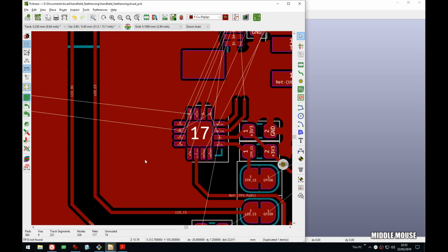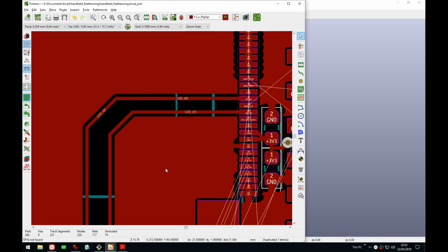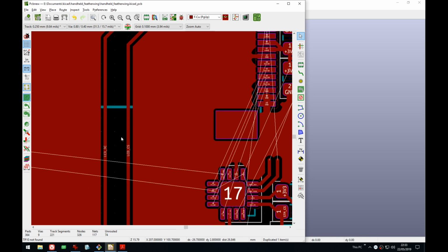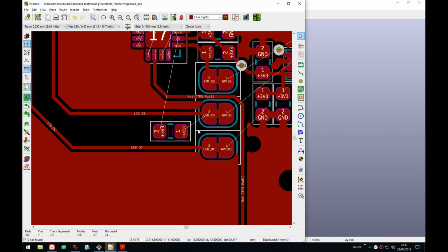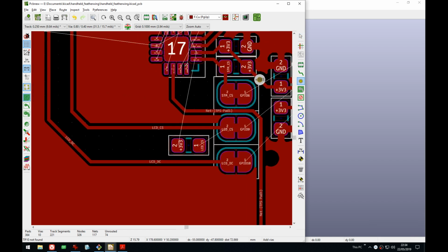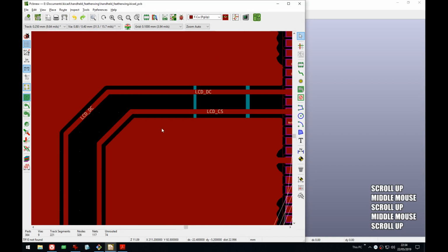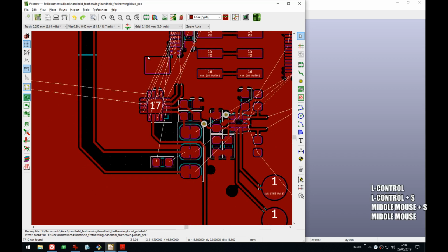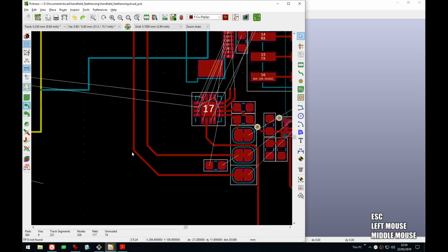Yeah, I guess it doesn't matter. Because what you usually want to do is put a ground plane between two lanes that might be high-ish speed, because there will be crosstalk otherwise. But right, and I just had the capacitor there. Oh, of course I did. Maybe it doesn't matter here so much because this is not going to be super high speed. But let's leave it like this for now, just because it looks cool.